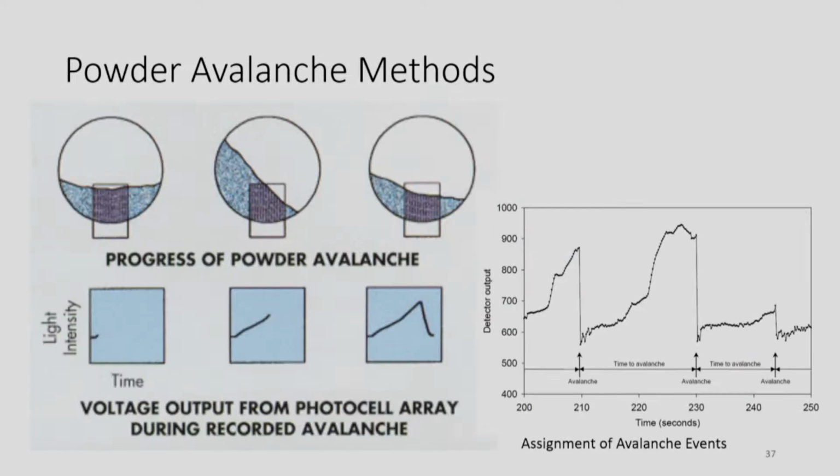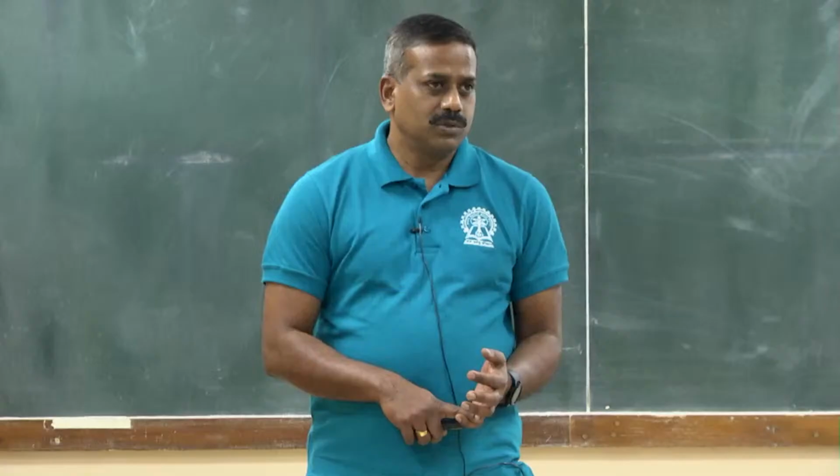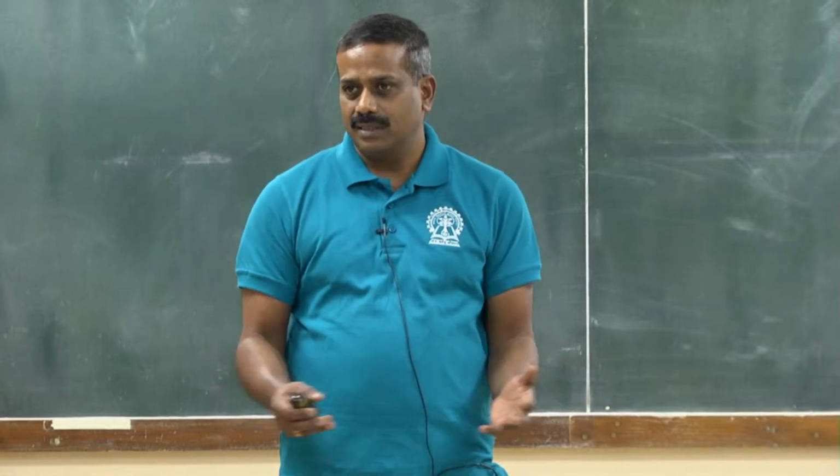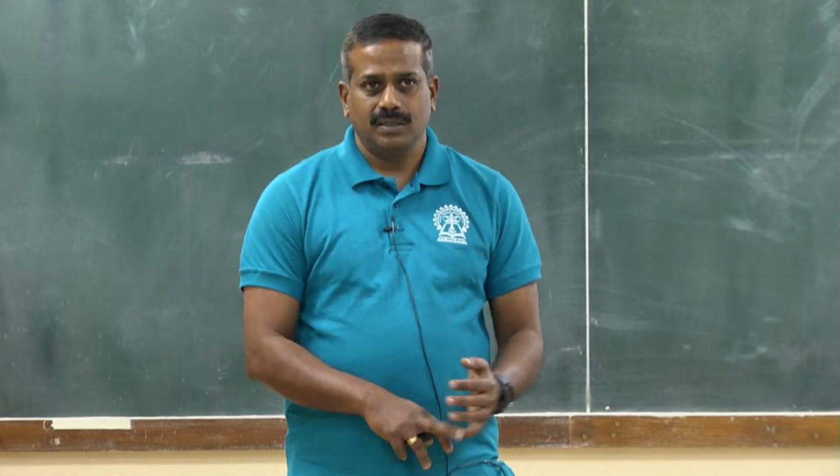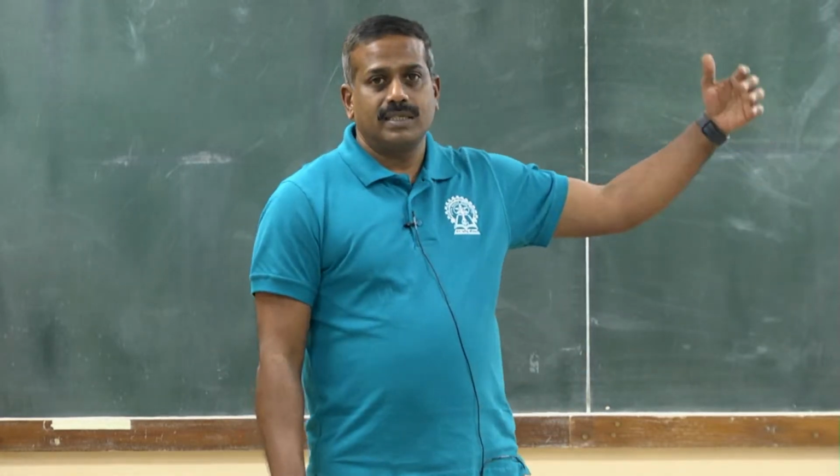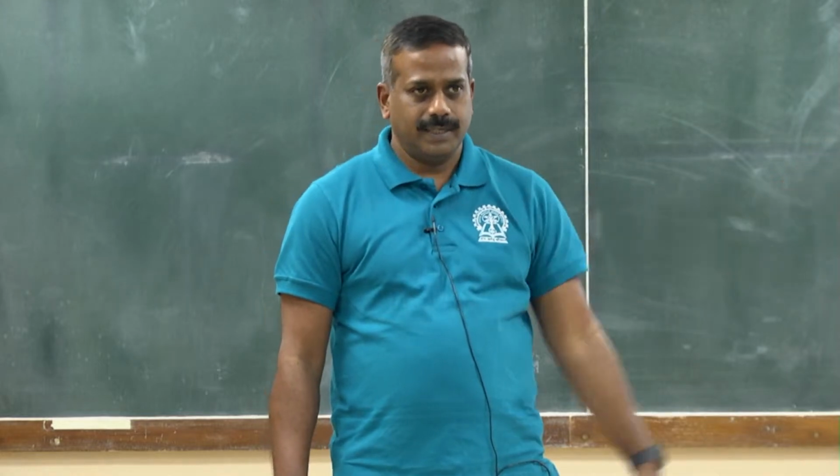Again, as I said, very simple and easy testing. You continuously monitor the change in angle at a specific place within the tester. So you get the angles at which the powder moves. It is most commonly used in mixing, formulation, etc., where it's very important to know the powder flow in a dynamic environment.